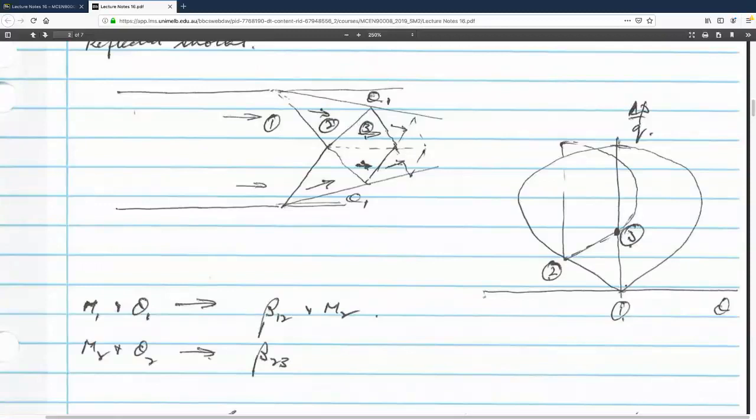So this shock wave here is transmitted into this region here, and that shock is slightly different from this shock. And then the flow is going horizontal, but here I have to turn the flow again. That's like this region here, I have to solve for this problem as well. So I have another oblique shock there. So I reflect this shock here, and I have another shock. So you can see I have a whole set of shock waves. It takes me back finally to subsonic flow.